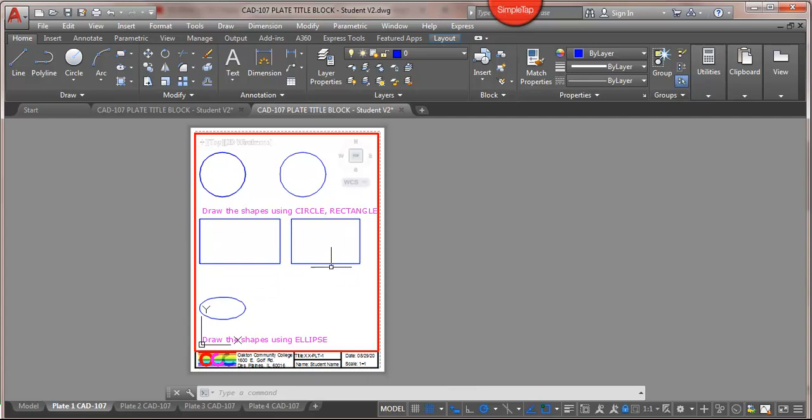If you do want to stretch it, you can click on it, and then it has these blue squares. If you hover over them, it gives you the dimensions of your parts. Again, this makes it really convenient to work with our machine tools. Then we can click on these grips, make them hot or red, and just scooch that over. Then I'll hit the escape key to clear off that grip.